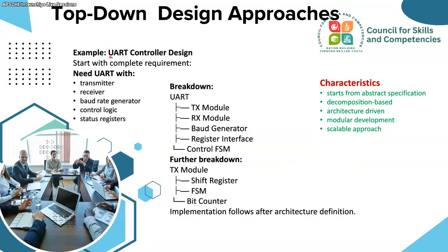For example, if we want to design a UART controller, we start with the complete requirement. What is the requirement? It must transmit, it must receive, it must generate the baud rate, with control logic and status registers. These are all the requirements. Then we go for a breakdown.